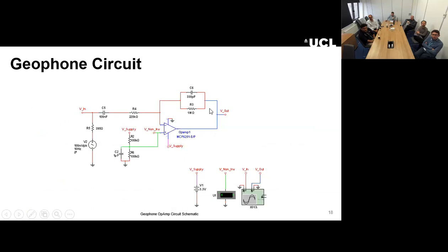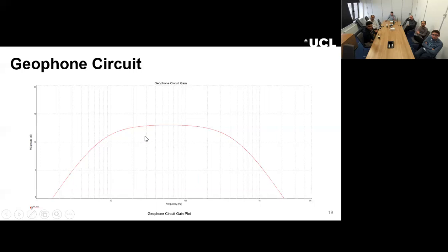And here's our geophone circuit. It also has similar specs to the microphone circuit, except it doesn't have a pot this time. And the geophone circuit has a bit lower gain compared to the microphone circuit because it tends to saturate easily when the vibration gets higher.